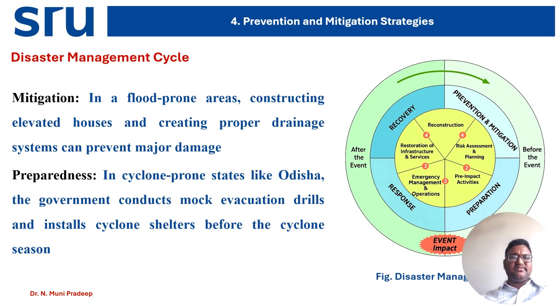The modern versions of this approach include constructing the plinth levels well above the documented flood levels, which will be given by the Indian Meteorological Department, building on raised earthen platforms, and designing proper drainage systems that can remove the flood water very quickly from the residential areas. Especially the Assam government has invested in raising the floor levels of schools and community centers in flood prone areas, which ensures that these critical community facilities remain functional even when surrounding land is inundated or affected.